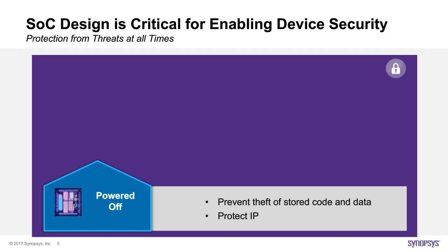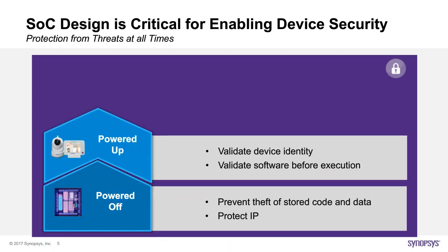So from power off, we go to the power up stage. Now the image and data is being initialized and used to execute and program the SoC. Do you need to validate the image and data on the device? If so, you'll need some form of authentication. What about the identity of the device and being able to securely ensure it has the right one? Again, some form of authentication and other process can be used to validate this. What is your boot up sequence? How many stages? Can you trust the functions being called at each stage?